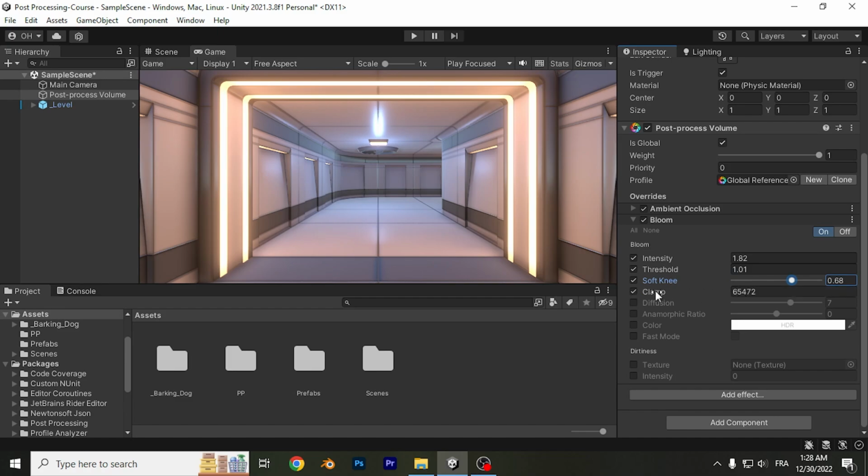Clamp. This clamps the pixels to control the bloom amount. Diffusion. This changes the extent of veiling effect. For highest quality, make sure your values are whole integers. It's advised not to animate this value, as it may cause small hiccups in the perceived data.